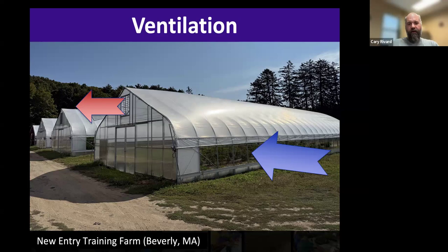So, again, if you are growing in the wintertime, really the winter or summer, I think it's really important to have that gable vent. But during the wintertime, there'll be oftentimes where you might use it where you're not opening the sidewalls at all and only using the gable vents to ventilate the tunnel.